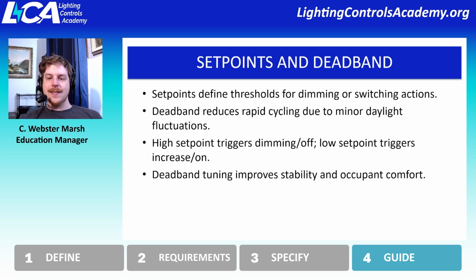So getting a sense of, okay, if it's a very small amount of light, you might not need a really broad deadband, but depending on the application and how variable that light is, you might get a sense of it by standing in the space, to understand, there's a lot of cars passing by and they keep flicking light up at the sensor.